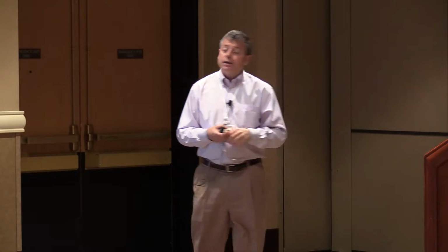Now, tunable white's a little bit different. Tunable white needs some intelligence. It needs some level of people making a decision what kind of fixture to use, what kind of control system to use. What we'll touch on are those considerations, because there's a consideration in the ceiling, which is what type of color am I mixing? I'll call it the ingredients, for lack of a better term. What's in the fixture that's going to give me a certain level of color and color control? And then on the control side, it's how am I controlling it? Is it a very straightforward 0 to 10 volt signal, or is it something more digital and more capable? So we'll start with the fixture side of it first.